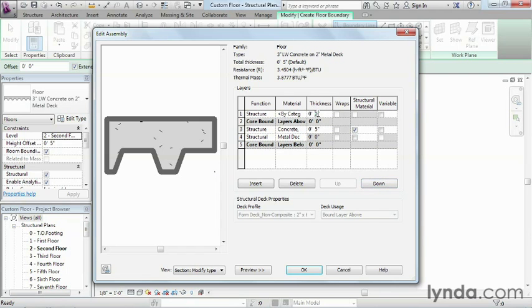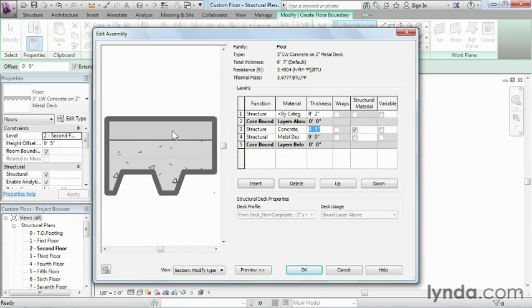Then if we wanted to give this a certain thickness, we could. If we wanted to have another 2 inches of thickness associated with this, we just add perhaps a number 2 here, click in this box, and now you can see there's another layer of material. It doesn't know what it is yet because we didn't click in this by category box yet.